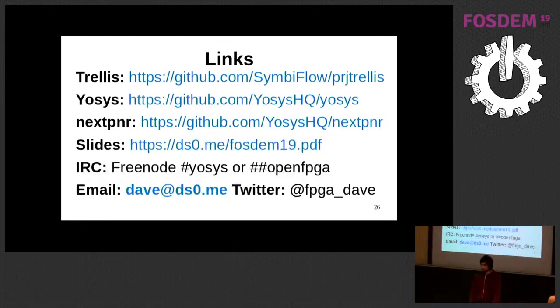For a given input, can the bitstream be the same for a build? Are you talking about against ourselves or against the vendor tools? No, is your system reproducible? It certainly aims to be reproducible, yes. There have been a few places where we've accidentally relied on unordered map ordering in C++, which tends to mean that it's reproducible on the same machines, but not on other machines. But I think we've got rid of all of those, so it should be reproducible now.